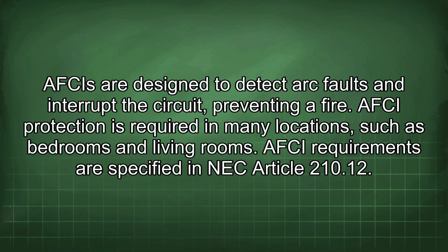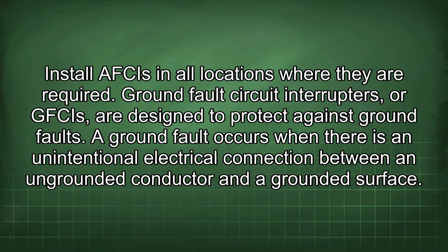AFCI protection is required in many locations, such as bedrooms and living rooms. AFCI requirements are specified in NEC Article 210.12. Install AFCIs in all locations where they are required.